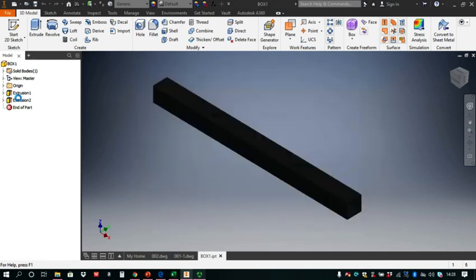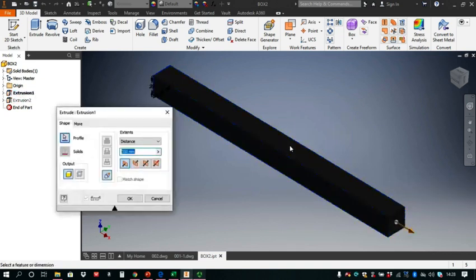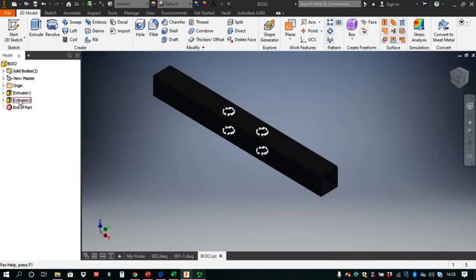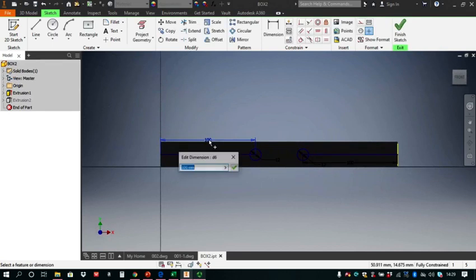Then I can go into the extrusion here, or here. We'll start with this one. Extrusion 1, change to 250 millimeters. Extrusion 2, I'm going to change the sketch this time, change this to 75, and change this to an 8mm hole.